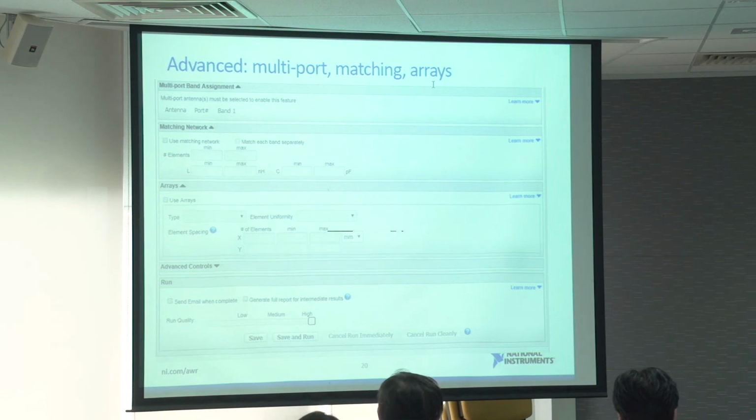And antenna arrays, we don't do antenna arrays that are, say, 200 elements, but we can do antenna arrays that are, say, maybe 16, 4x4 or a 5x5, because every array is simulated with a 3D simulation, and so we can simulate subarrays, and then you can extrapolate your array performance from that if it needs to be bigger. And then next slide.